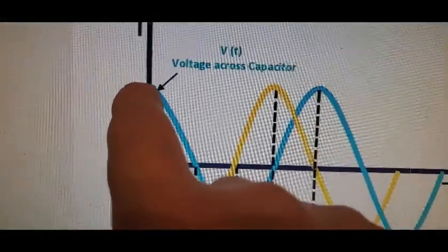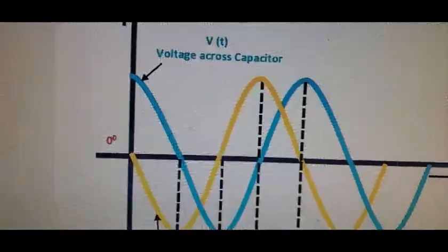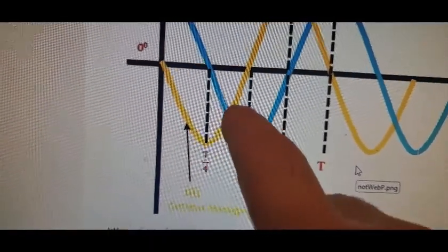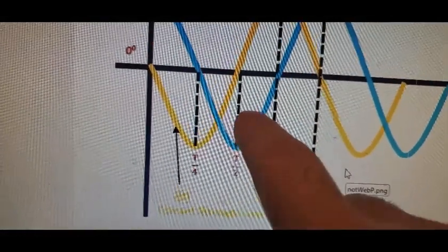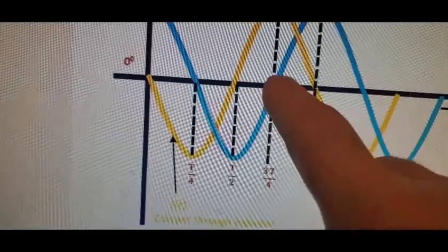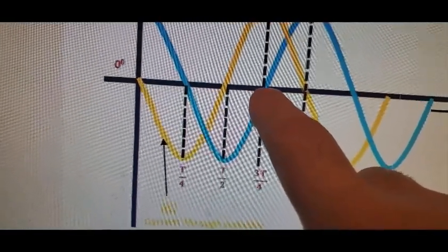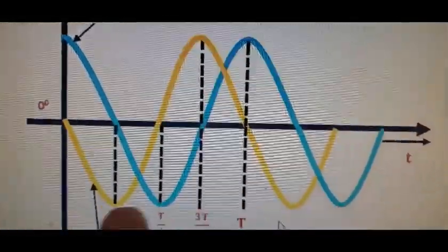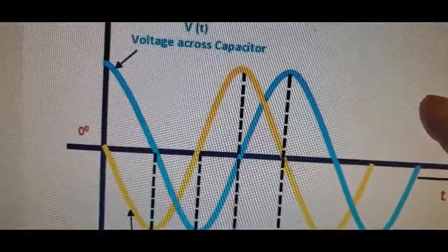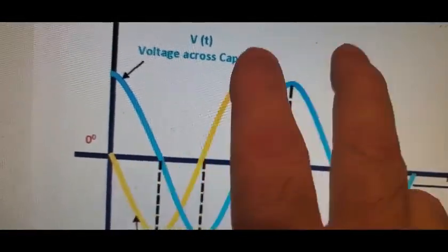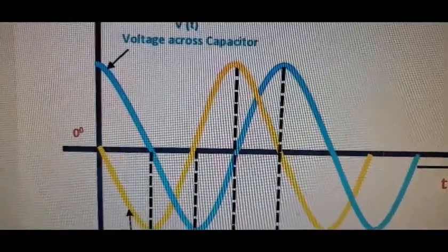Now, let's say this is 10 volts. It goes to 0. Your amperage is now maximal. Current reverses. This goes negative. Now the current is 0 in the inductor. This discharges. Now the voltage is 0 in the capacitor. This is maximal. And they're showing a perfectly undamped oscillation. And you note that the voltage and the amperage are 90 degrees out of phase.